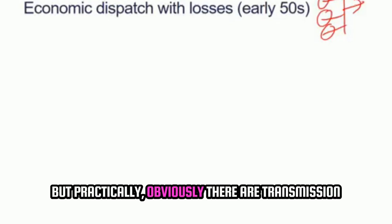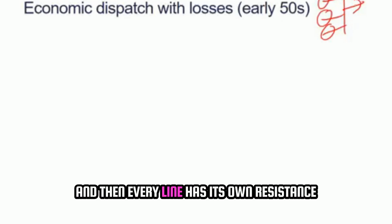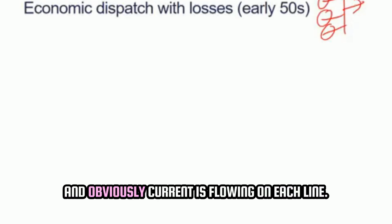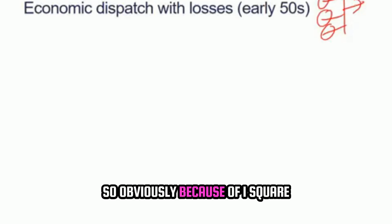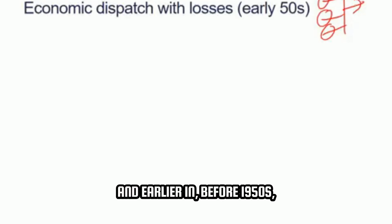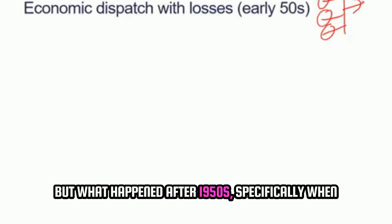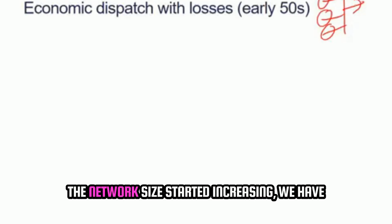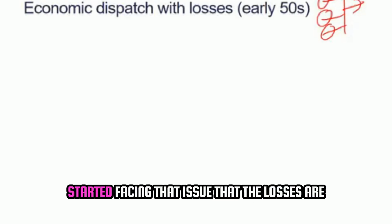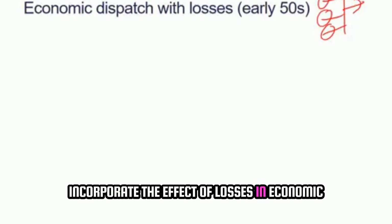But practically, obviously there are transmission lines, and every line has its own resistance, and obviously current is flowing on each line. So because of I square R, there will be some losses of power. Earlier, before the 1950s, this was not much of an issue. But after the 1950s, specifically when the network size started increasing, we started facing the issue that losses are increasing to a very high value, and we have to incorporate the effect of losses in economic dispatch.